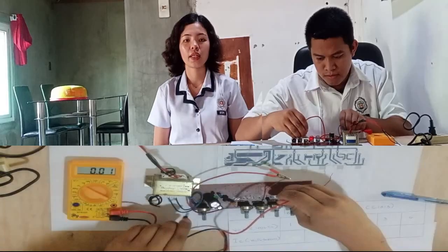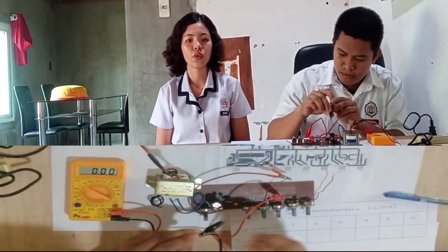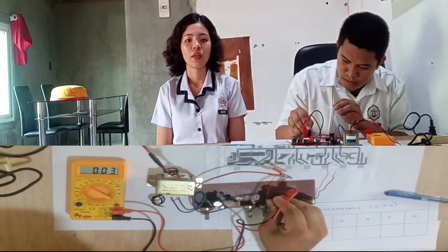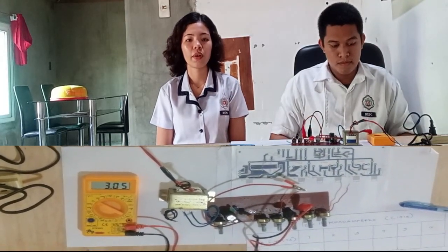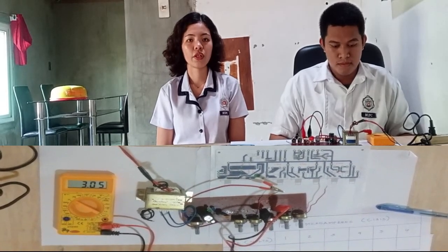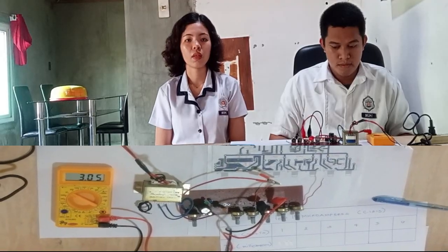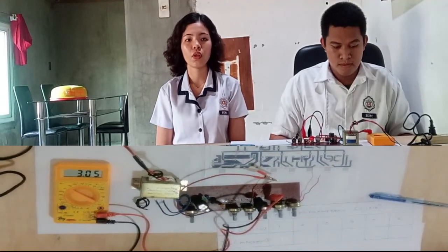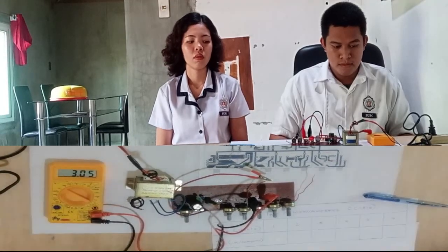Since R3 is connected to the transistor's collector, our calculated value of current also represents the collector current flowing through the transistor. We record this value of collector current in milliamperes immediately below the collector emitter voltage value of 1 volt in the table provided in Figure 2-4.